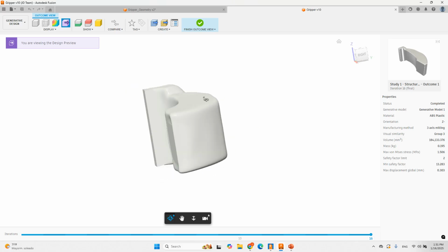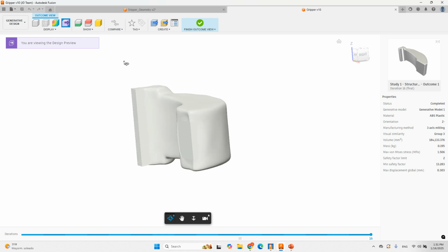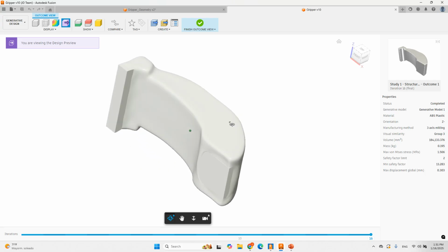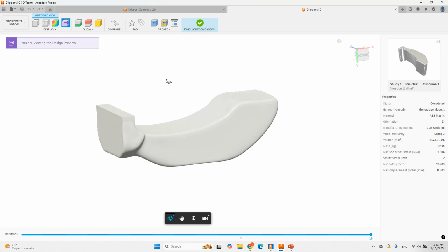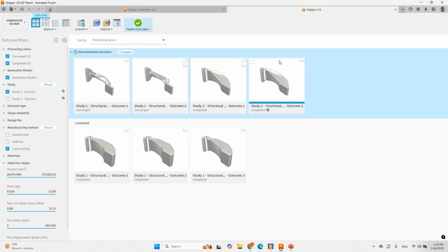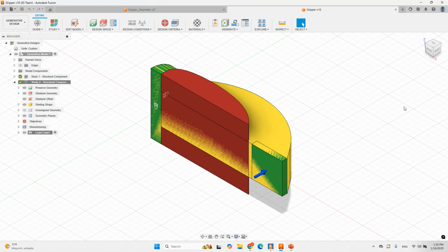In case I need to start with a block like this, and all I've got in my shop is a 3-axis machine, it would probably be a better idea to try to do this from this orientation. That's for the Y direction, right? That would be why you might want to explore different solutions and different orientations from your original setup.